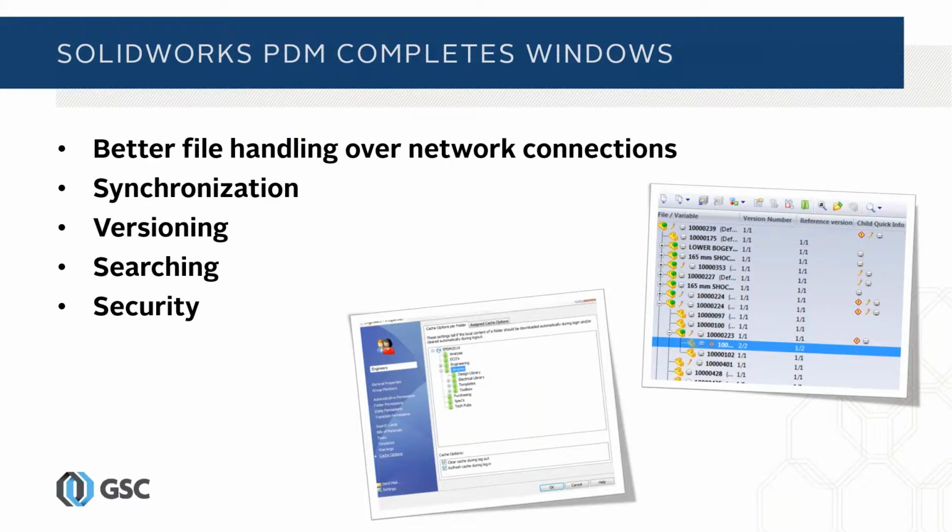And it copies those over with an operating system level copy, i.e. much less lag comes into play. And then SOLIDWORKS is basically told, okay, go get the file and open it, but it's from the local C drive. So mechanically, it's much, much better. There's all kinds of other things that PDM does, but just from a performance standpoint, the plumbing, how the network works, it's worth it just for that, in my opinion.